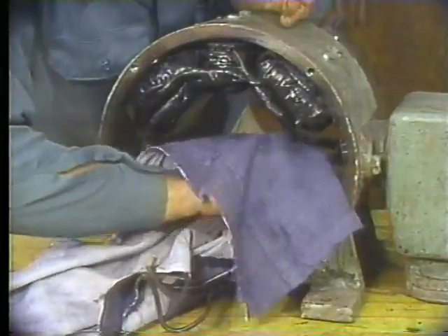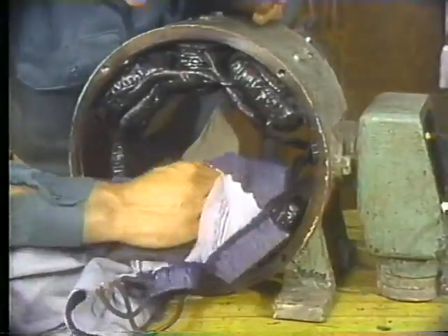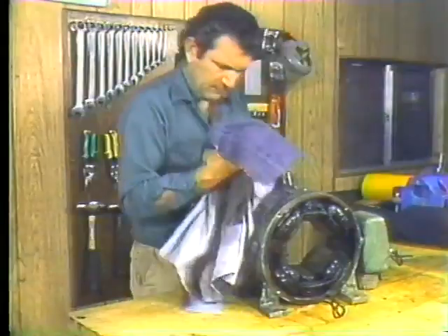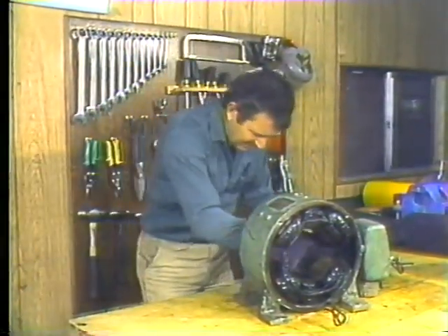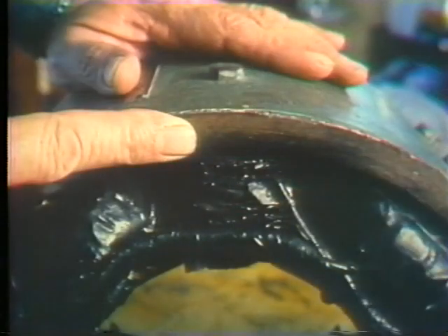Next items on the list are the motor frame and the field poles. They've got to be cleaned real good first. Pay special attention to the area between the main poles and around the interpoles. Clean out all the dirt and carbon dust. Okay, now it's time to check the field coils. Carefully inspect them. Look out for cracked or broken insulation. Be sure to examine the interpoles too. Repair any damage to the insulation using the insulation varnish.